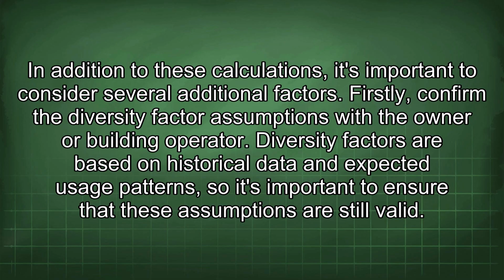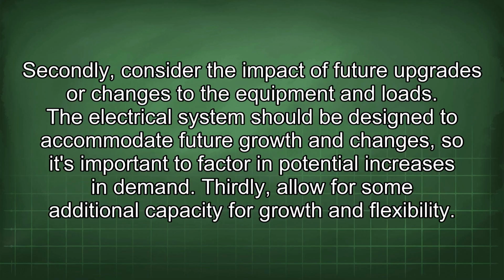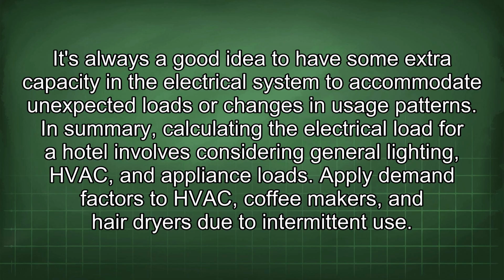In addition to these calculations, it's important to consider several additional factors. Firstly, confirm the diversity factor assumptions with the owner or building operator. Diversity factors are based on historical data and expected usage patterns, so it's important to ensure that these assumptions are still valid. Secondly, consider the impact of future upgrades or changes to the equipment and loads. The electrical system should be designed to accommodate future growth and changes, so it's important to factor in potential increases in demand. Thirdly, allow for some additional capacity for growth and flexibility.